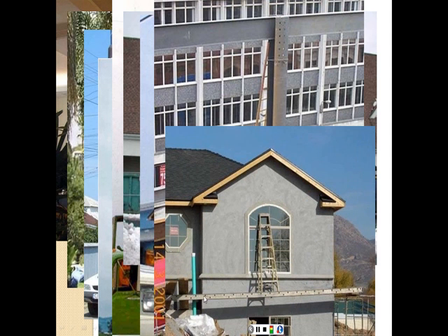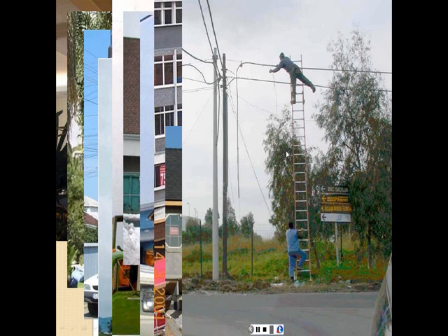Resting the ladder on another ladder and resting it on glass, which can break and cause injuries. The slope here is not 4 to 1. Again, 3 or 4 different violations here. Notice that these are all actual pictures taken from actual construction sites or construction related activities. Genius.